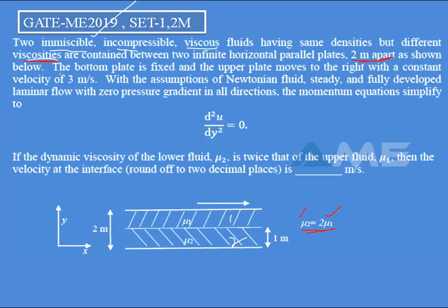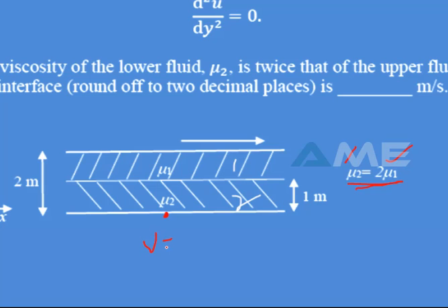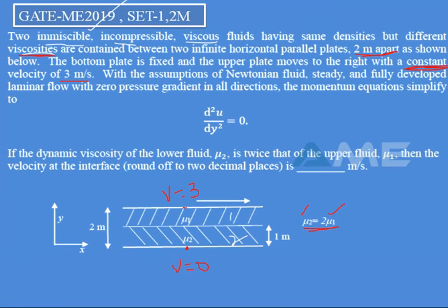The bottom plate is fixed and the upper plate moves to the right with a constant velocity of 3 meters per second. So you have to observe this. Here the velocity is constant. The lower plate is fixed, so there your velocity is equal to 0. The upper plate velocity is constant, which is 3 meters per second. With the assumptions of Newtonian fluids, steady and fully developed laminar flow with zero pressure gradients in all directions, the momentum equation simplifies to...